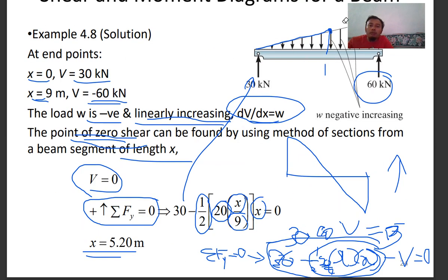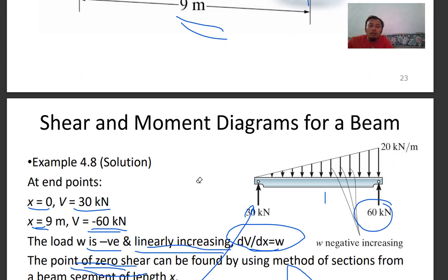For example, when you are drawing your shear force diagram, you see here it's 30 kilonewton upwards, and your triangular loading downward is almost zero at the starting point. So you can expect the value to spike up to 30 kilonewton, then it goes down as the load increases up until that point, your roller, and then it will spike up to zero again.